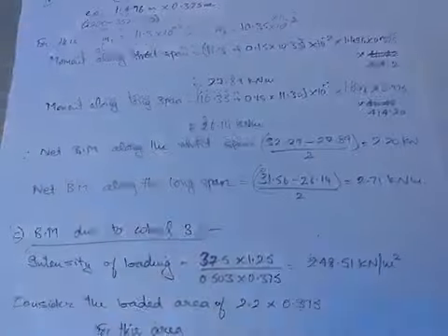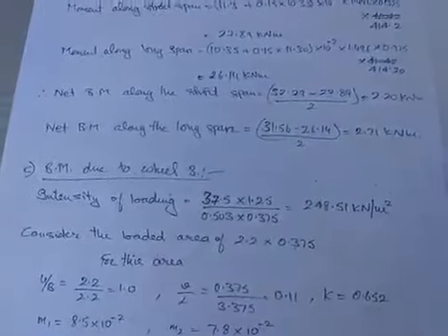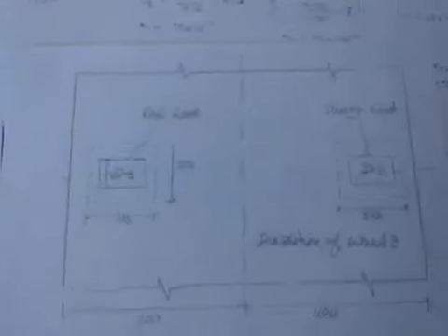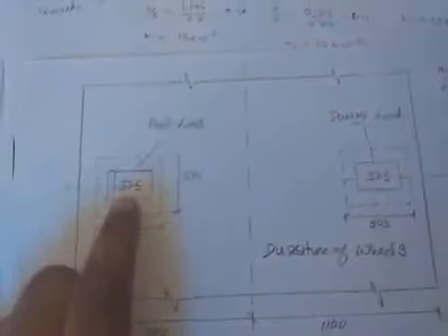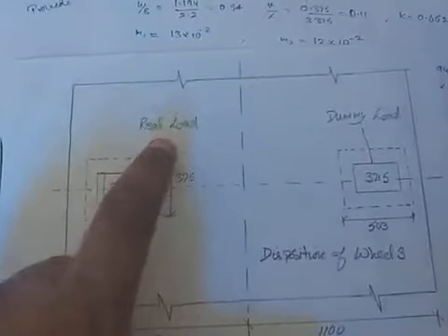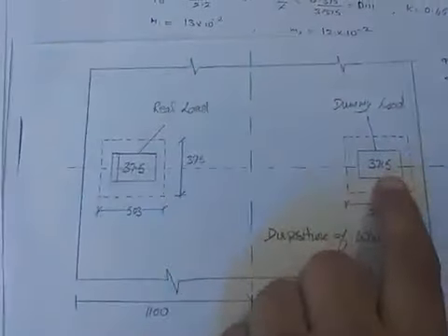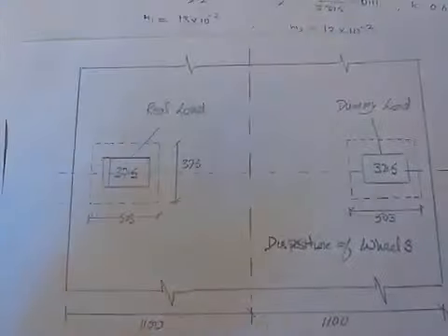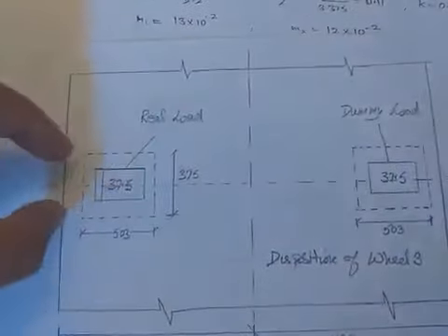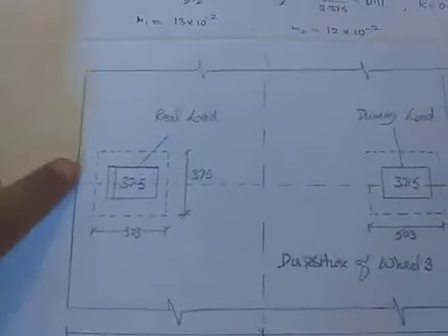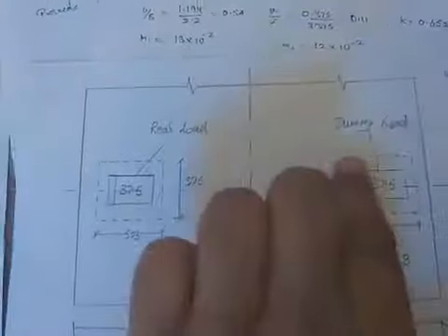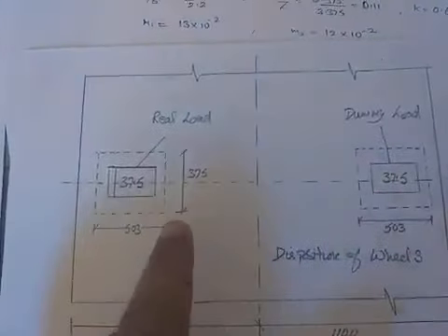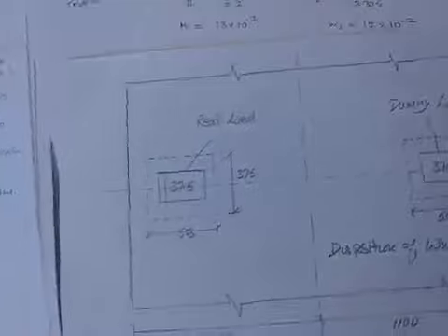Likewise, we will do the calculations for wheel 3, wheel 4, and wheels 5 and 6. So for wheel 3, let me show you the load placement. Wheel 3 is placed like this. Again, we see that wheel 3 is asymmetrically placed. The real load is like that. I have placed a dummy load over here. We will take first the full strip and find out the values, and then we will take the area where the load is not there, this one and this portion and this portion. We will subtract that and divide it by 2 to get the actual result.